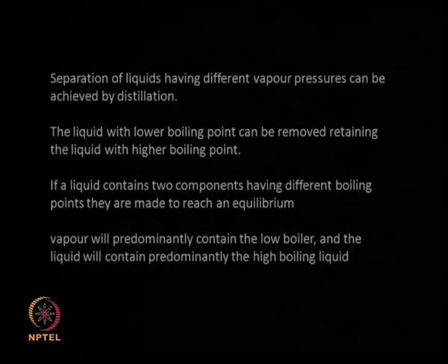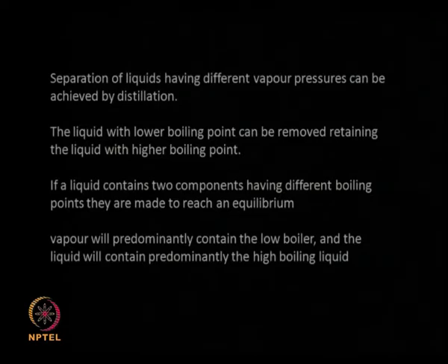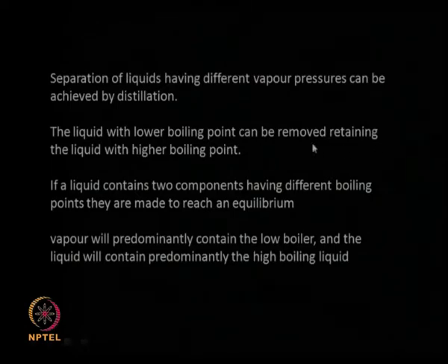So it is good if you want to separate liquids having different vapor pressure. The principle of operation is based on vapor pressure. When I heat a mixture of liquids, the liquid with lower boiling point goes into the vapor, whereas the liquid with higher boiling point remains in the solution.